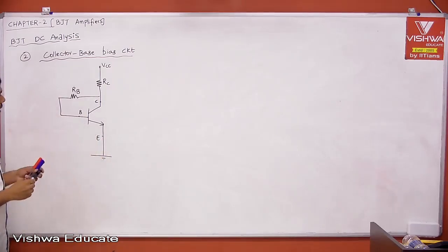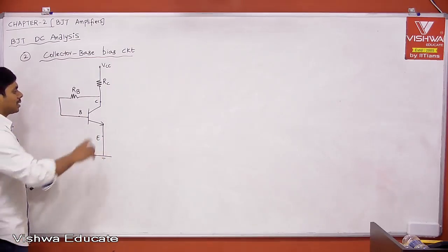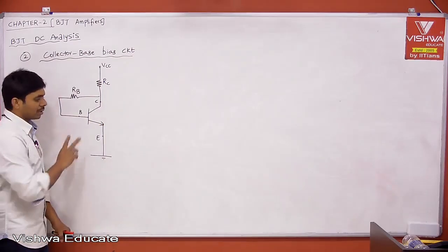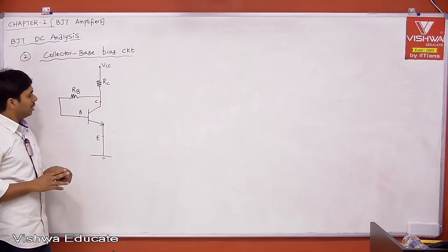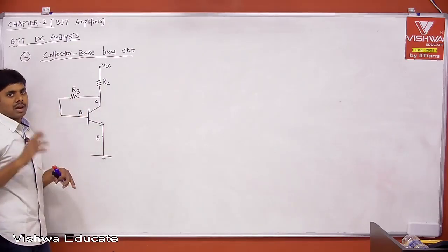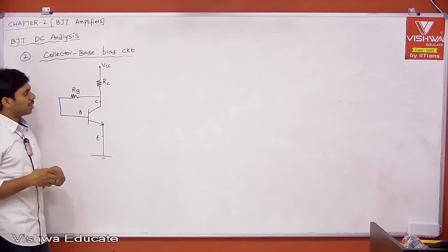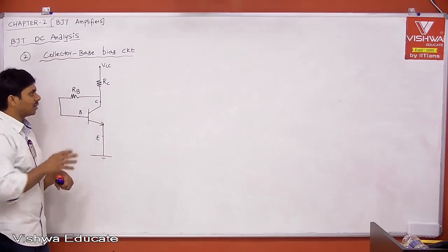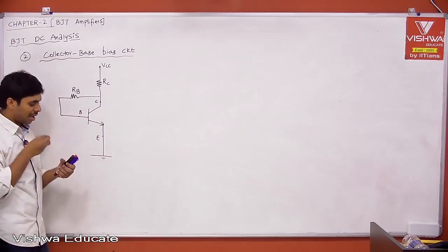Listen, okay. Now let us say VCE is greater than 0.2, VBE greater than or equal to 0.7. To get those things, we have chosen RB, RC such that we are getting those things. Transistor is kept in active region, but whatever voltage, output current, that is the Q point, that should be stable. Yes, because of this configuration it is stable, but how it is stable, I am explaining.